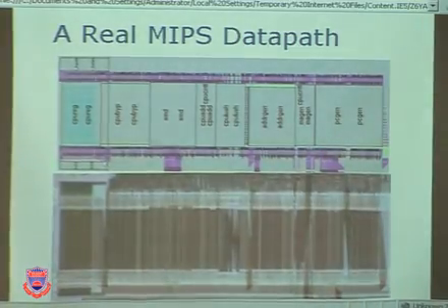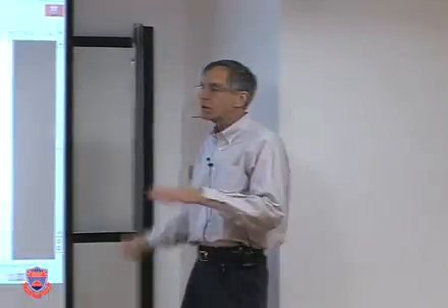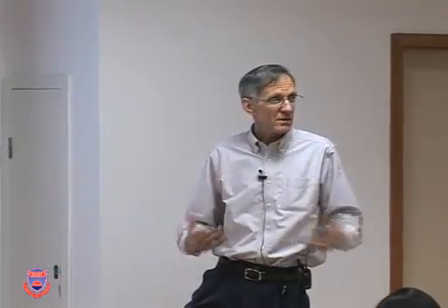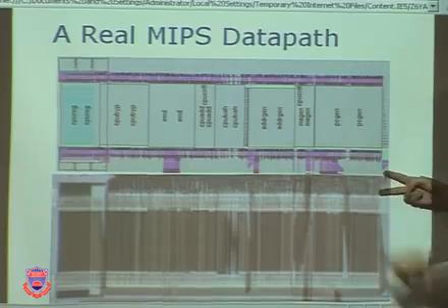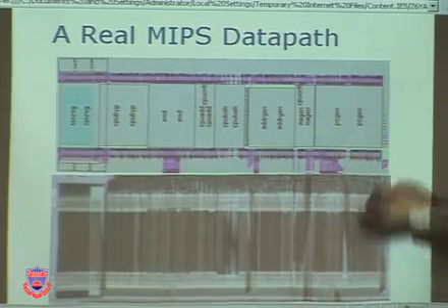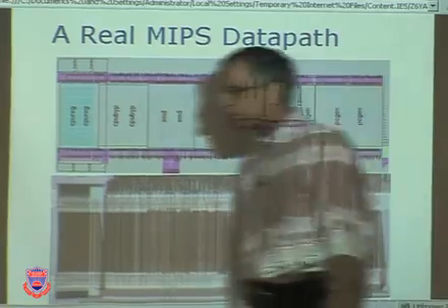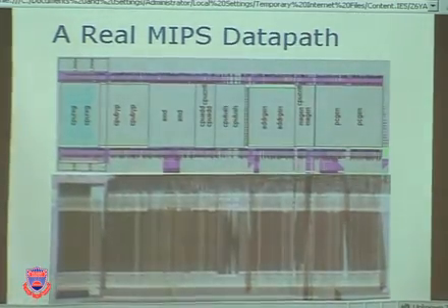So the idea is regular structures, good layout, fast buses, connection of things that need to be nearby each other. So that's called a floor plan. The layout is based upon a floor plan, how to use the chip area effectively for fast circuitry and for effective signals to be communicating quickly with low noise, with minimum power rather than maximum, minimum interference, etc. So that's the floor plan. And then when you zoom in, you've actually got transistor layout and cell layout on a micro level inside here. Okay? So that's just for your information.